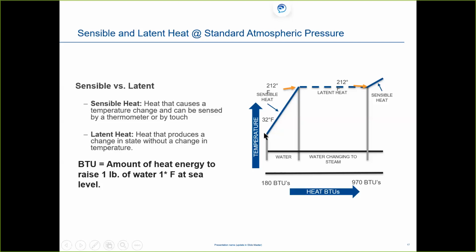Now all the ice is gone, so the water starts to warm up. We get to 212, we're boiling. So this is our boiling point for water. This is where glide will take place on normal refrigerants with several or multiple components, different refrigerants. We get to that 212, all the liquid's gone. We hit 213, that's going to be 1 degree superheat, or 1 degree sensible.